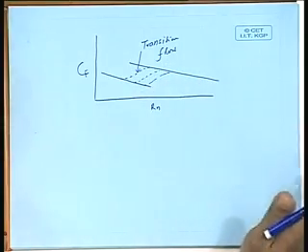Take for example a ship. We know that the model is much smaller in scale. Therefore, if I take the Reynolds number VL over nu for the model, then it will be much smaller than that of the ship. So the flow in the model may be in a totally laminar region, and it will be more so if the model is smaller. Can you understand that?